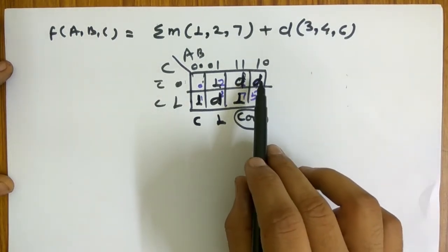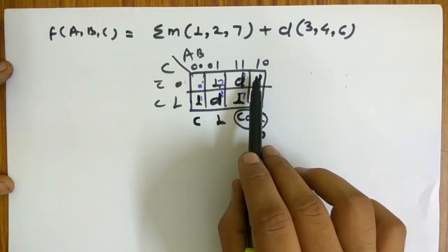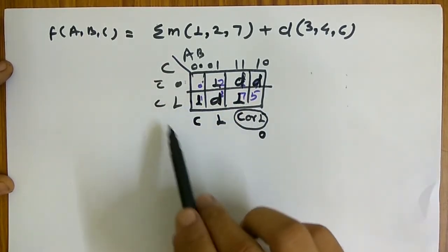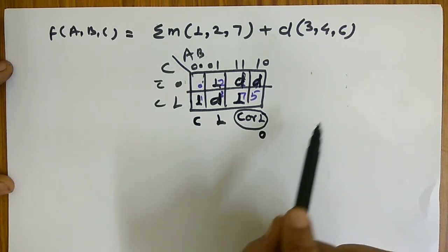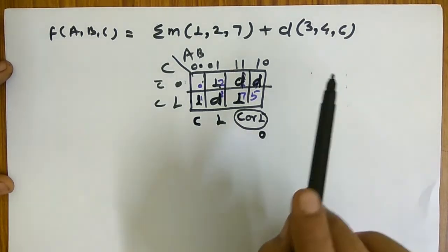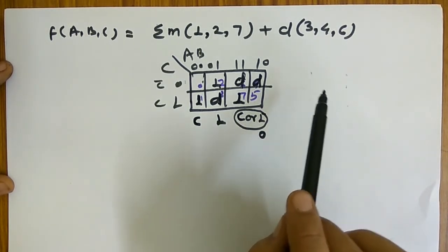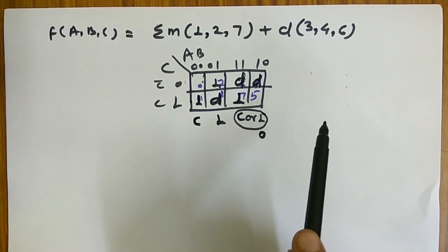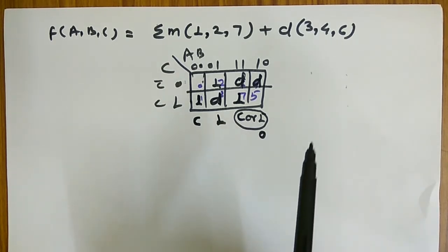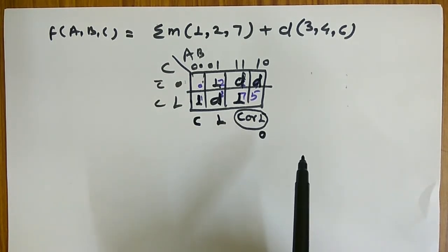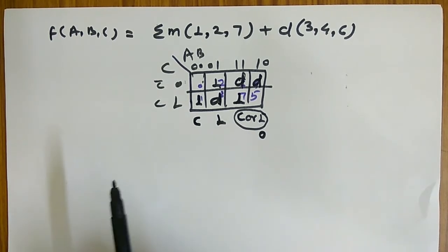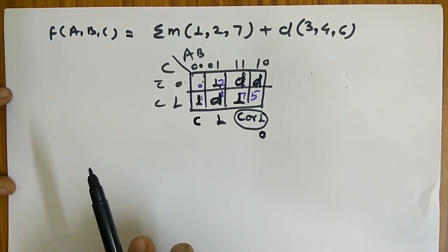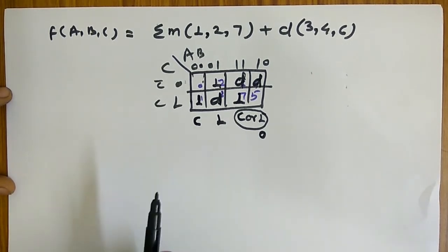So we have to eliminate inverters, so we will use d as 0. So this is the concept that we have to use don't care in a manner so that the inverters in the circuitry should be reduced. So we have to try to reduce the inverters. So I have completed all the topics regarding implementation of any boolean expression into the mux.